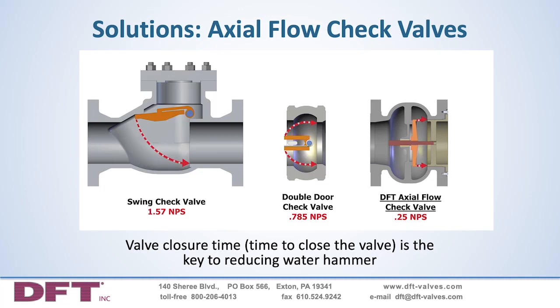And the valve closure time is the second key to reducing water hammer. So the axial flow design really does come out ahead by both closing the valve before flow reversal as well as closing the valve faster.